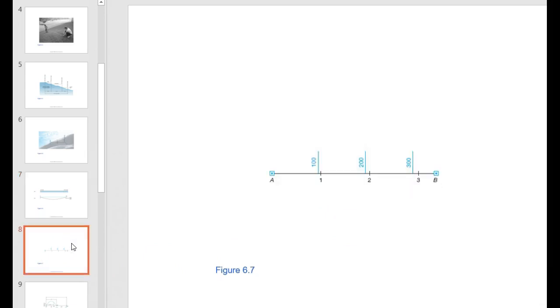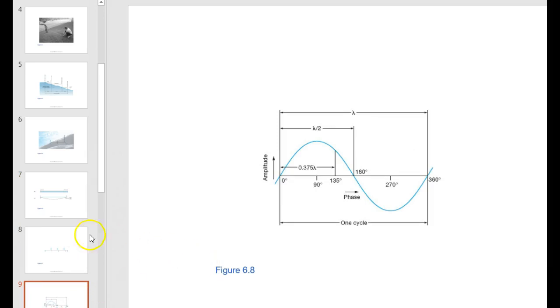So one of the things that we start to talk about then is a total station. And a total station measures in a completely different way. The distance that's measured by a total station is equal to some full number of wavelengths plus some partial wavelength that returns to the total station after it hits the prism, divided by 2. So in other words, you set up a total station instrument. It sends out a series of light waves, bounces off the prism, and returns.